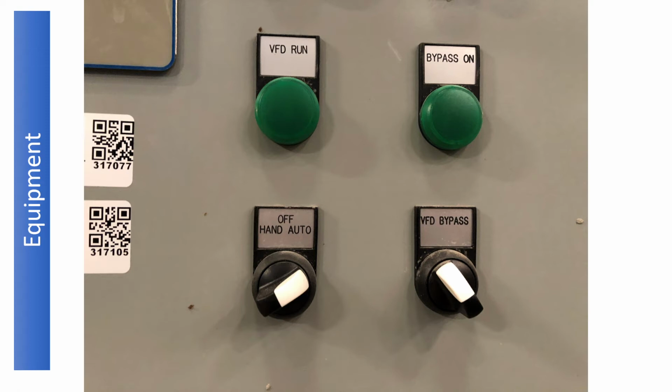And we didn't really talk about the building automation system too much yet, but all of this equipment that we see is being controlled by a computer. And that computer is called the building automation system. The BAS, every industry has its acronyms. So the BAS receives signals from temperature sensors and flow meters, which we'll see. And then via the programming, it commands the pumps and the chillers and the staging of equipment to respond to that load. So when a piece of equipment is in auto, it's actually getting that commanded signal from the building automation system and will slow down accordingly.